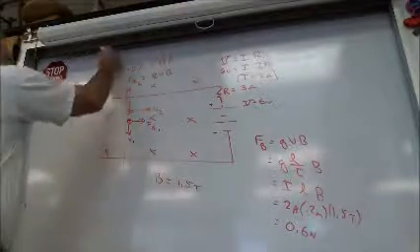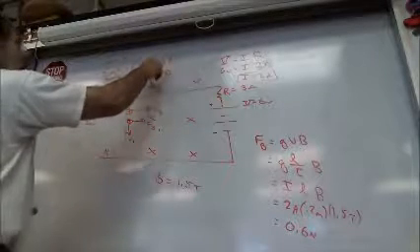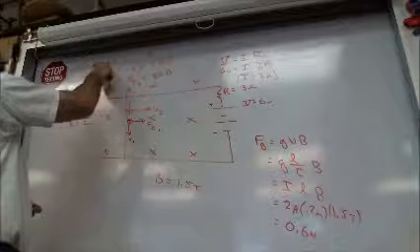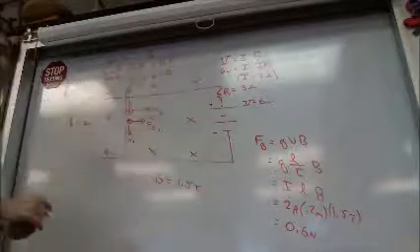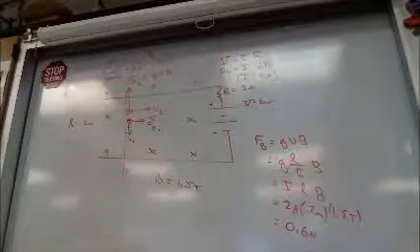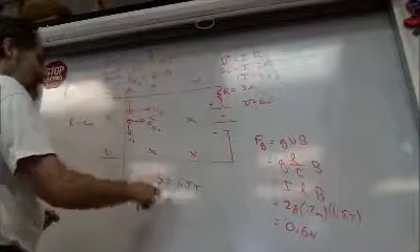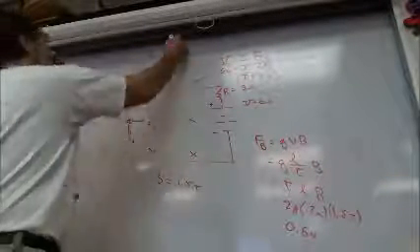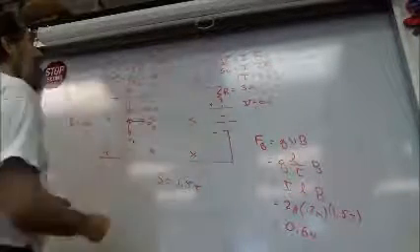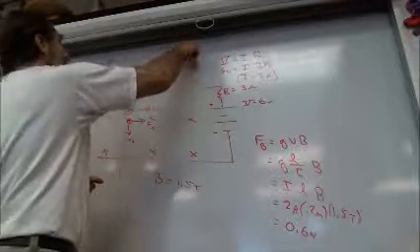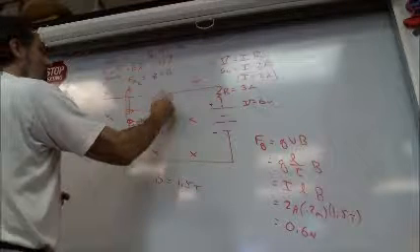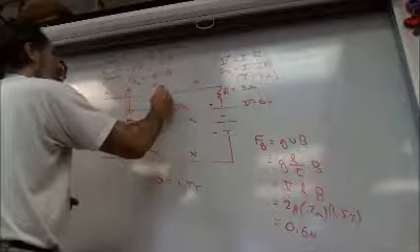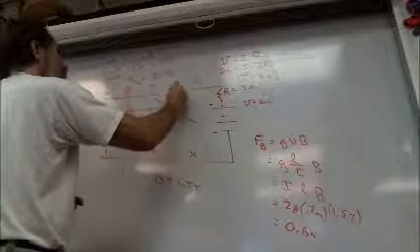So let's write up here 6 volts equals vBL. We don't know what that velocity is, but when that is 6 volts, we call that a terminal velocity. Do you see I put the little t there? Okay, terminal velocity. What's the B field? 1.5 Tesla. What's the length? 0.2 meters. And what do we get for a terminal velocity? 20 meters per second. Okay, 20 meters per second for a terminal velocity.